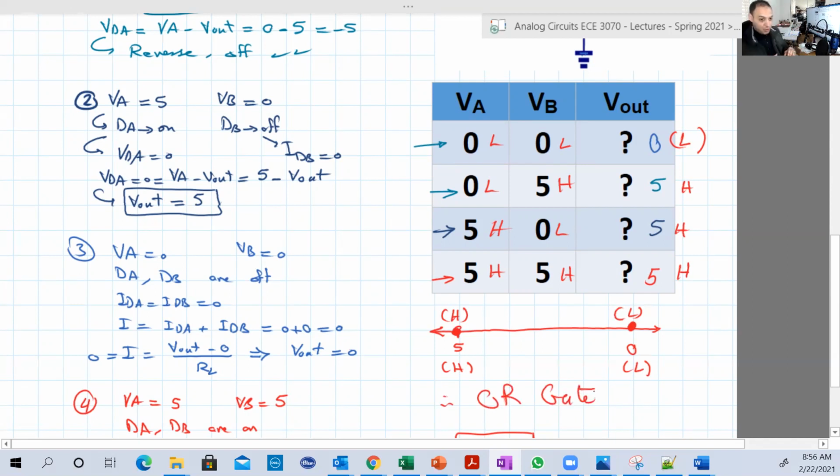So, although V out was different, V out with the same circuit when you solved it before using a constant voltage model was 0, 4.3, 4.3, 4.3. Okay, but still 4.3 or 5 or 5.5 or 4.9 or 4 point whatever, all such voltages are closer to high, which is 5 in that case, rather than 0. That's why they all consider the same thing, high.